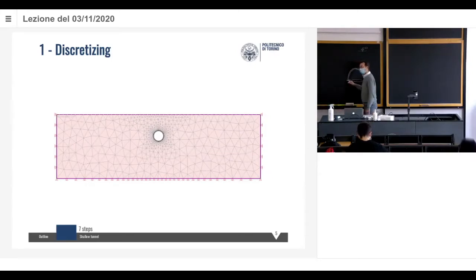So just to define our construction stages, okay? We're going to excavate this tunnel. We're going to excavate the upper part first, then the lower part later. But before we excavate the lower part, we install what we call the primary lining. So this is going to be the primary lining, maybe light blue. Right? So this, let's call it primary lining.